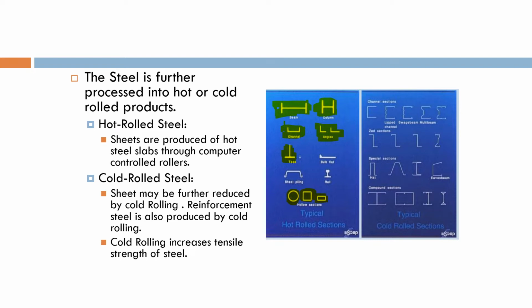Whatever imperfections are on the surface, they get rid of by turning. Then there is grinding, which you already know, that it narrows the original size tolerance and creates a similar kind of surface over the whole member. And there is polishing, which improves the surface finish.